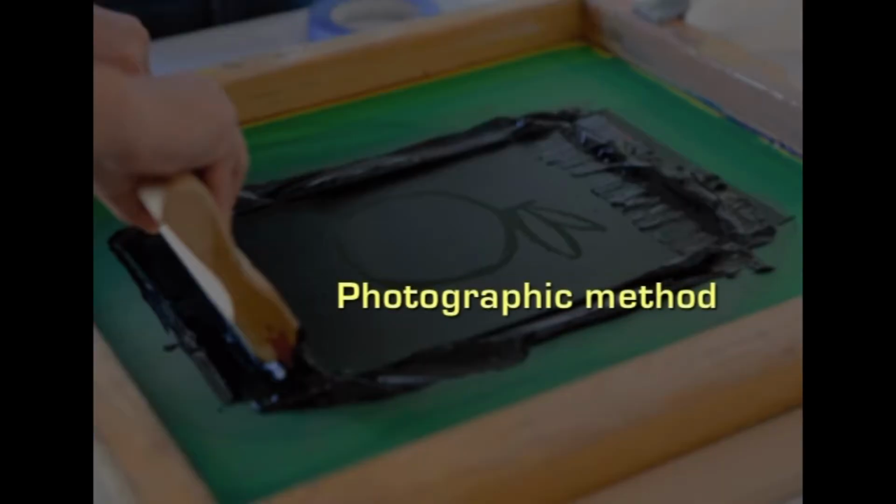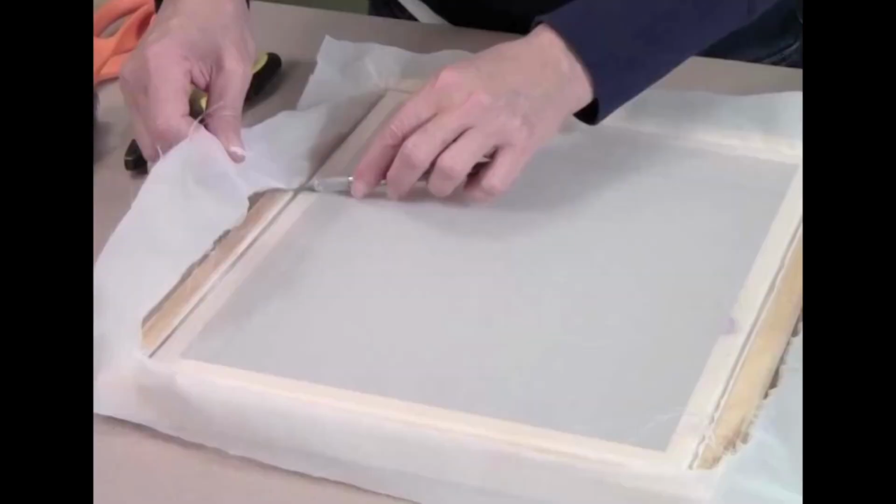Coming to the fourth method, the photographic method. Today, the design is photographed and a negative is used for producing screens. This method requires considerable experience and skill and is very widely used. Silk bolting cloth stretched on the screen frame is coated with a sensitive solution of gelatin dichromate and is dried in the dark. The portion of the design depicting one color is drawn separately on a tracing paper with dense opaque black ink, which is called a positive, is placed in contact with the sensitized screen and is exposed to light for a short time.